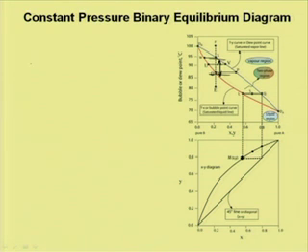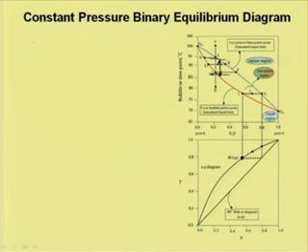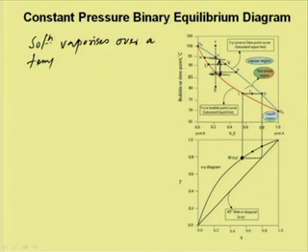This is the temperature region where the liquid is vaporized. Except for a pure substance, the boiling point of a solution does not have any meaning, because the solution vaporizes over a temperature range, which is starting from the bubble point to the dew point.